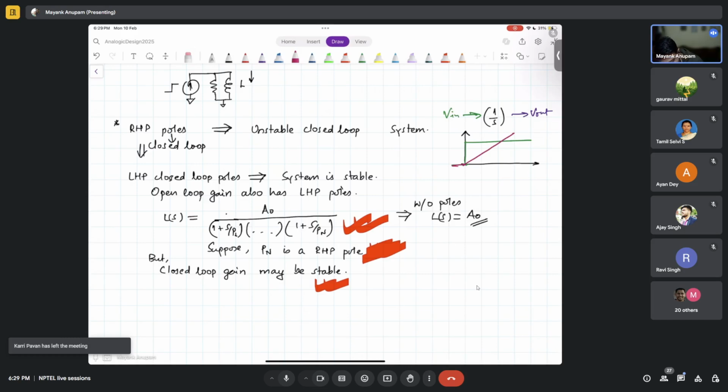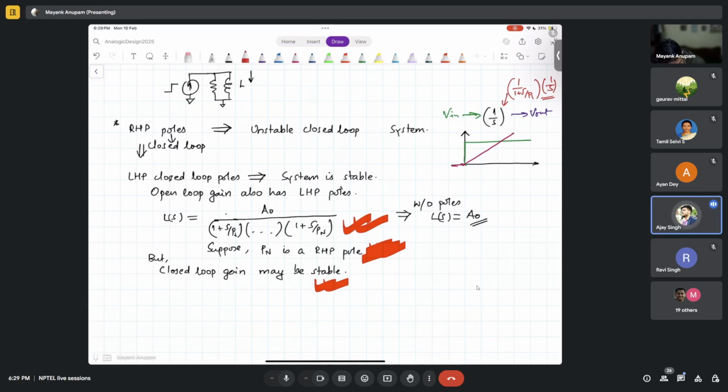Now tell me, the system which had one more pole, something of this kind, 1 over 1 plus s over p. So basically, it was something of this kind. It now has an integrator, and there is also a delay, right? So what was the response of this system? A right shift by 1 upon P. Yes, it looks something of this kind, right? After a very long time, it looks like there is a delay of 1 over p1, right?